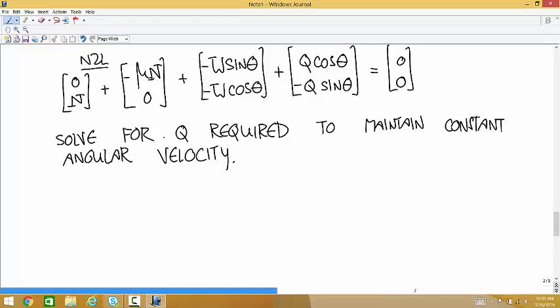All right, so we're going to solve for this Q. Basically, we're going to figure out, for that certain amount of weight, how hard it is to turn this screw. We have two equations. So the second equation says, if we rearrange it, N is equal to W cosine theta plus Q sine theta.